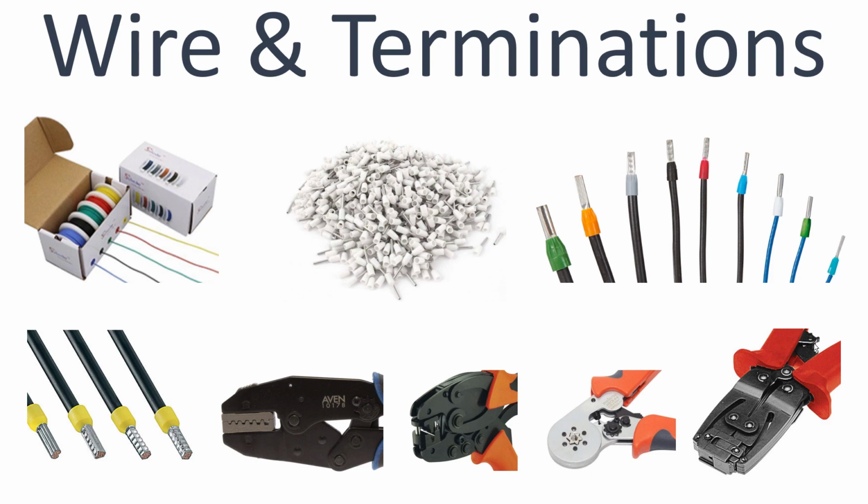Okay, wires and termination. I always use MTW, machine tool wire. It has a softer insulation. It looks better. It's easier to handle. And I always use stranded and tinned. Very important. If you're going to solder, you want the wires tinned. And then I ferrule everything now. I use these crimp ferrules on anything that's not soldered.